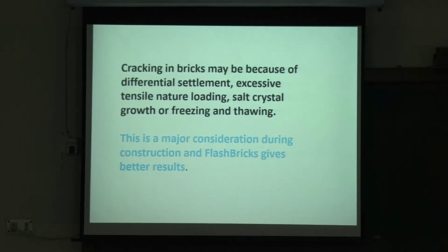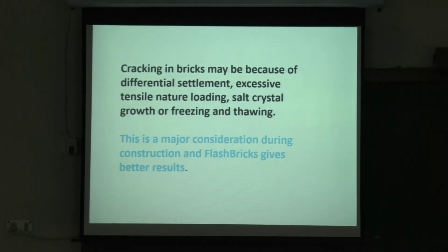Cracking in bricks may be because of differential settlement, excessive tensile flexural loading. Tensile flexural loading is when you have a brick wall, there is a tremendous amount of force coming down. The lower part has much more load, okay?